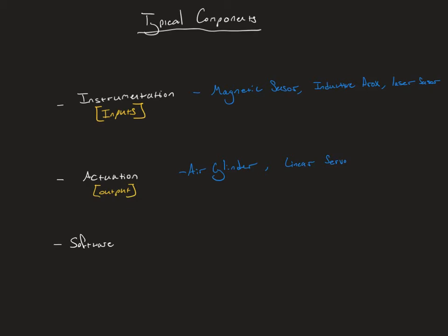So when we're talking about software in a PLC, typically we're talking about output control, input feedback, input back checking, and data handling. Some of that would be obvious. Output control is the logic that controls when an output would be on or off, or if it was some sort of continuous output like an analog output, to what level is it on.